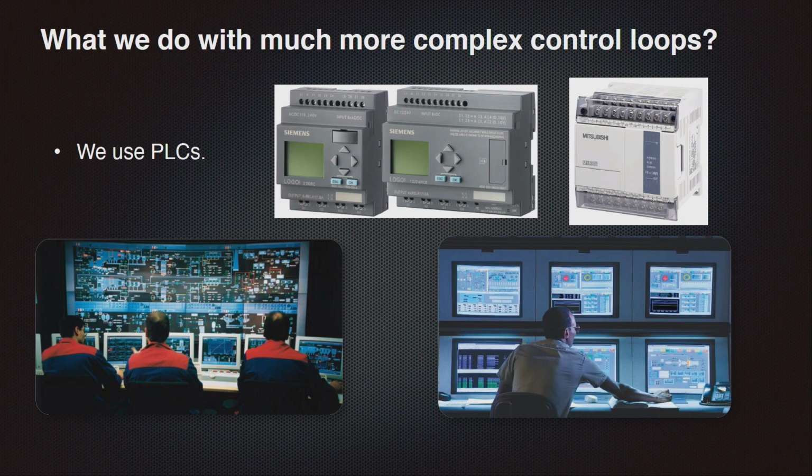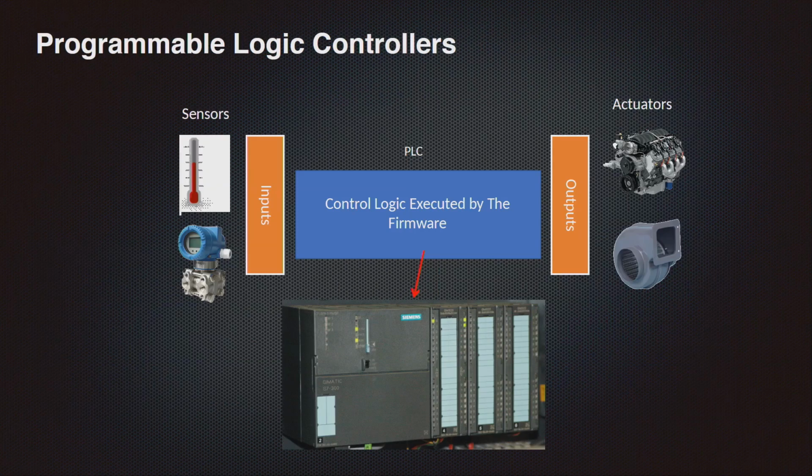And what we use for this is PLCs. Here is a diagram of how this typically works. You can see here it's the inputs, which are typically sensor values. This could be like a temperature. This could be the level of a liquid inside a tank, something like this. And then there are outputs. The outputs which steer actual motors, actuators, and something like a pump, for example.